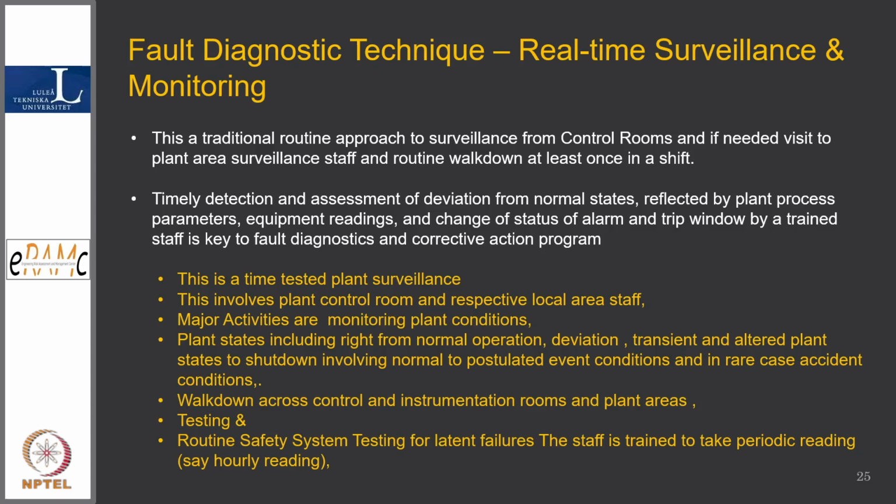90% of the time, it is some minor corrective action that is required: start something, stop something, close a valve, open a valve. If it is electronics, then repairing the card or replacing the card is the easiest thing that can happen. If it is an electrical system and some alarm is there, then you see why the alarm has come. It is some under voltage relay that has failed, or some problem is there, because the actual power supply has failed, and now our plant dedicated power supply system, captive power, diesel generator and all, are starting. So, it is a transient situation.